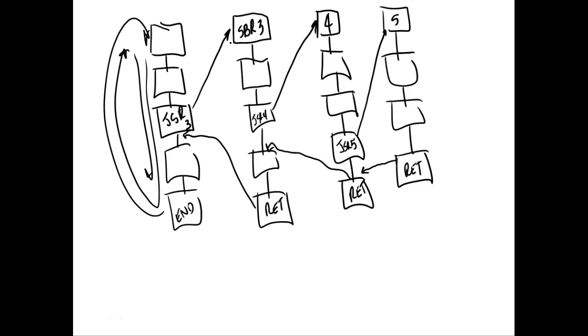And we call these guys what? Nested subroutines. And what is a nested subroutine? A subroutine within it calls a what? Subroutine. And that's what's so neat about that stack. It's last in, first out. So every time it sees the JSR, it pushes the return information on the stack. Then the next one, it pushes the return information on the stack. The next one, it pushes the return information on the stack. And then when it says that first RTI, it doesn't pull everything, it pulls the top of the stack, right? And then when it gets the next one, it pulls the top of the stack.